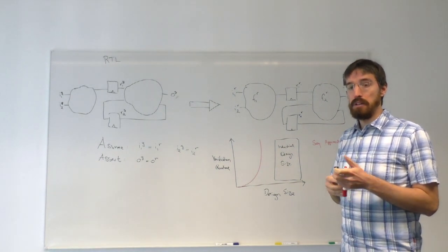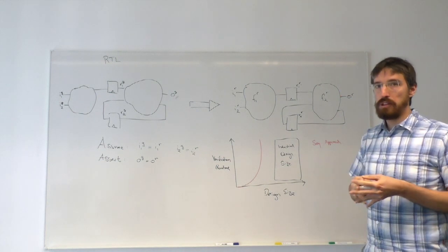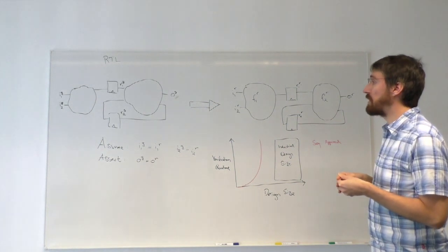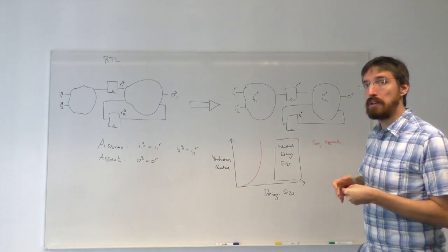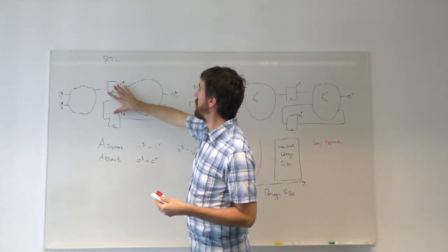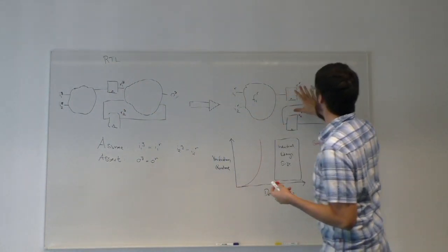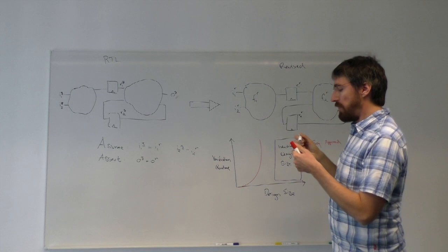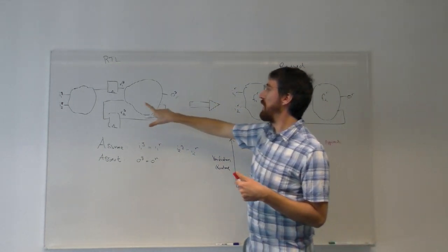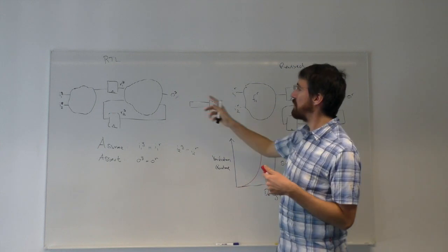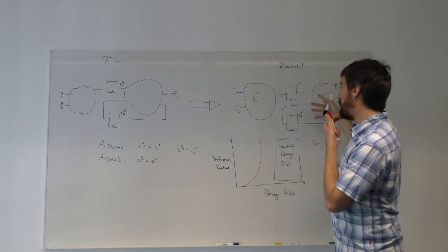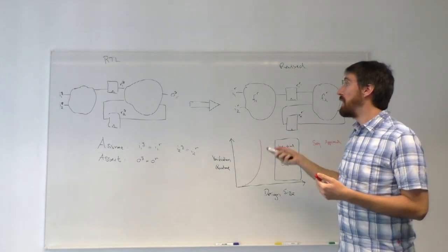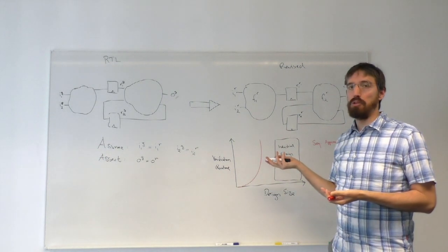Well, what's the workaround? The workaround here is that you need to give some hints, some information, to the prover. And as I alluded to in the beginning, the structure between the RTL and the revised design, I should write that down here, they are similar. Even though the logic clouds may have changed, you still have that with respect to the sequential gates. They are at the same location, so they have a structural similarity. And this structural similarity you should let the tool know about.